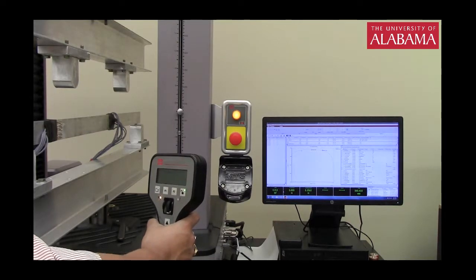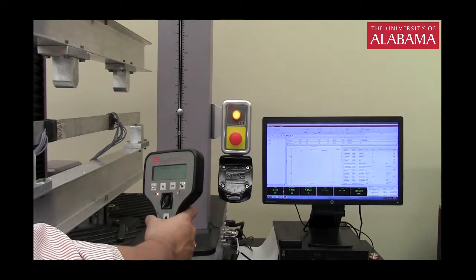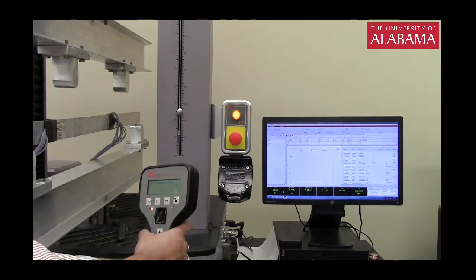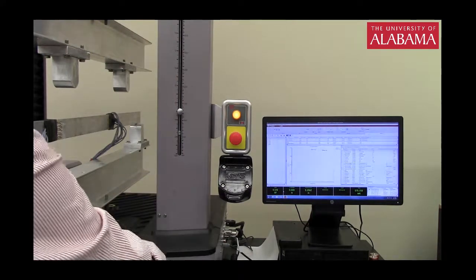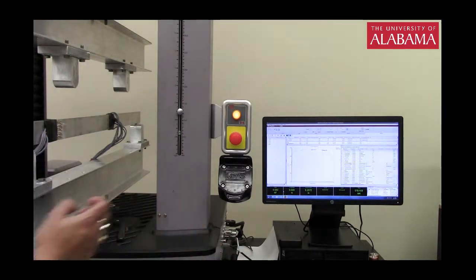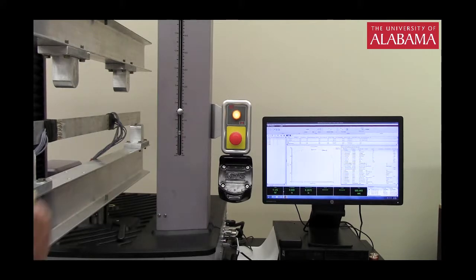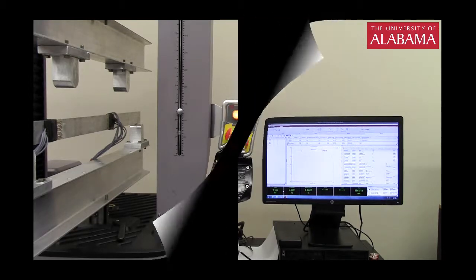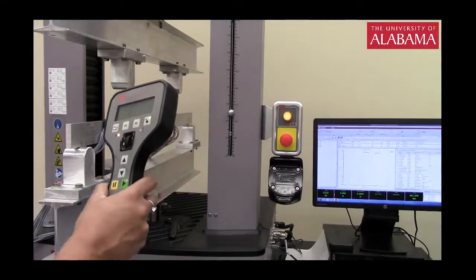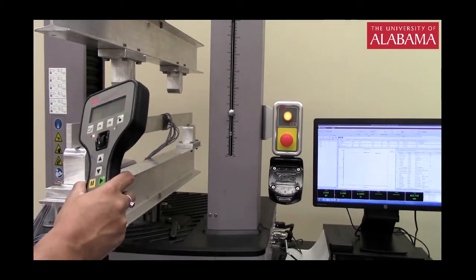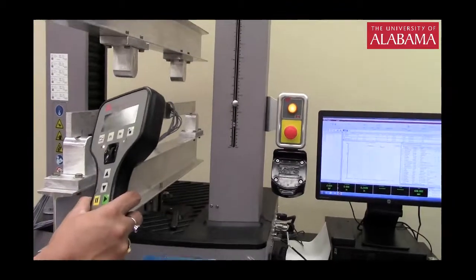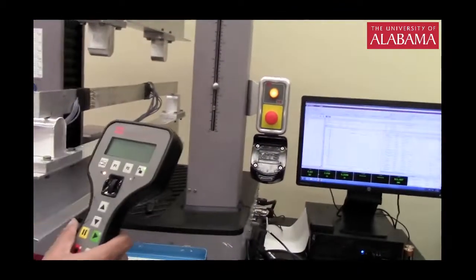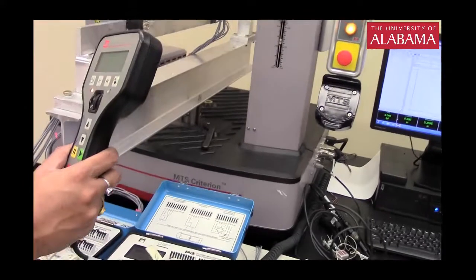If you see the manual on your computer, you will see that it gives you a table where you need to fill in the data. So the very first thing you need to do, before we move any further, is to go ahead and record the data for the 0 load. Right now you can see that it's 0, so we are going to record whatever strain gauge readings we have for 0. I'm going to call out the gauges like 1, 2, 3, 4, then 6, 7, 8 and 9, and then 5. We won't worry about it right now. I'm going to tell you in a moment why 5 is not that important.